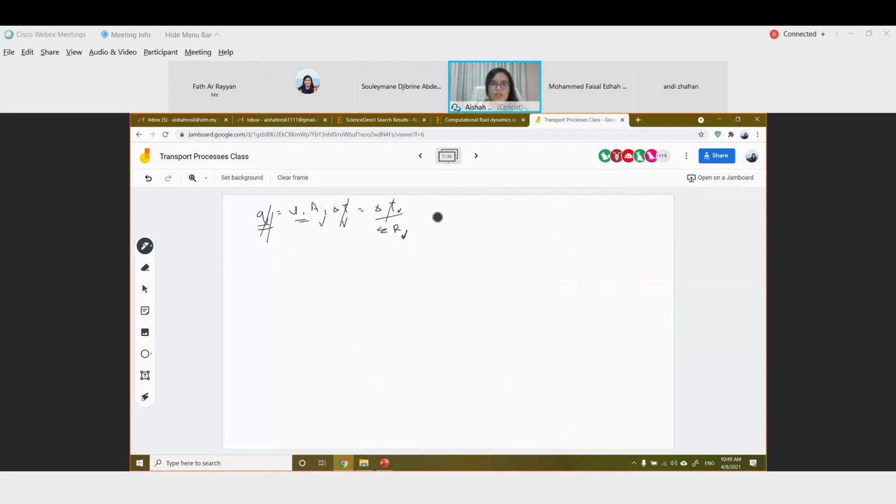You can rearrange the equation to be UI equals 1 over AI times the sum of resistances. For AI, we already calculated it to be 0.0255 meters squared, times the sum of total resistance just now, 0.008852 Kelvin per watt.